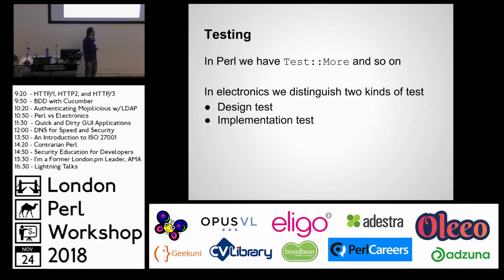And then you have more your implementation test, in that here I've now built my PCB, I've soldered all my components onto the board. Have I done it correctly? A lot of these components, maybe I put one in upside down, or maybe that leg there hasn't quite soldered on properly and it's not made a connection or whatever. So you have this distinction between the two kinds of testing. Does this design work, and have I implemented it properly?